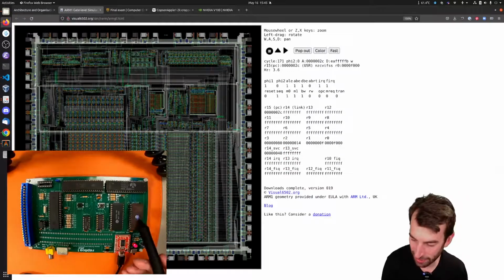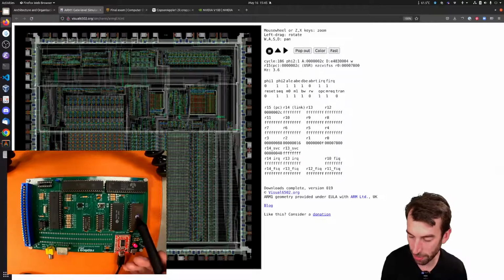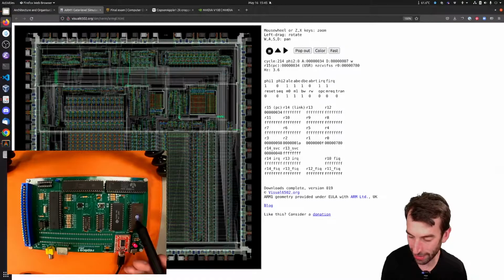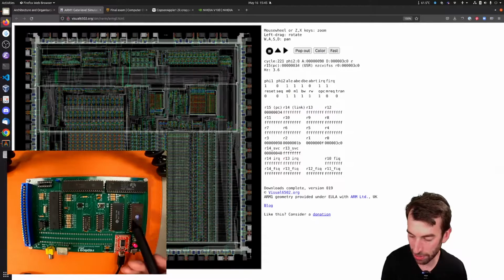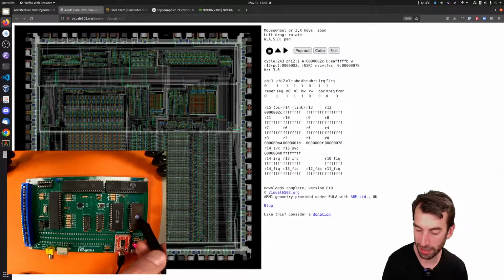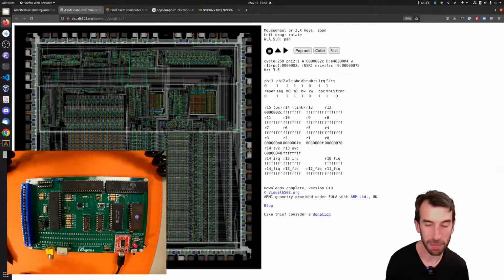You can see that little square inside there, that's a silicon die for this ROM chip. If you look closely, probably not in this video, but in the pictures, you can see tiny little bond wires that are connecting those legs from the silicon die to the legs of the chip package. Probably the ARM1 would be a bigger die than that, but probably not that much bigger.